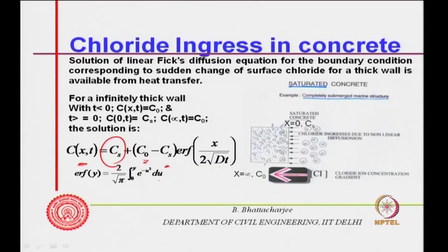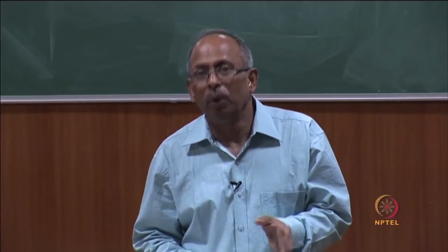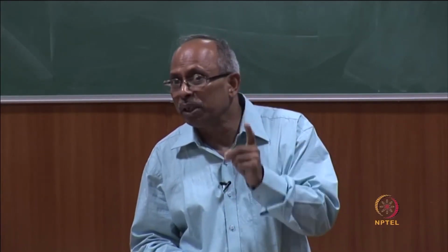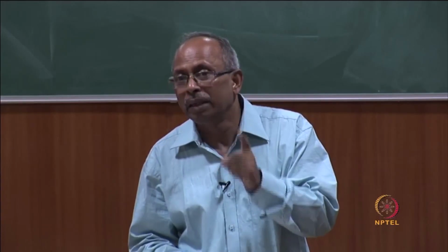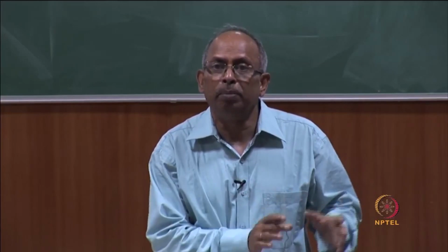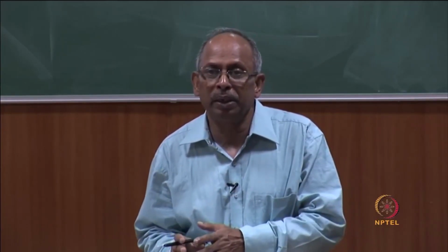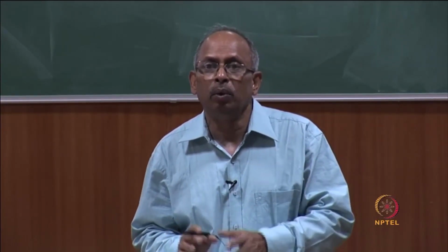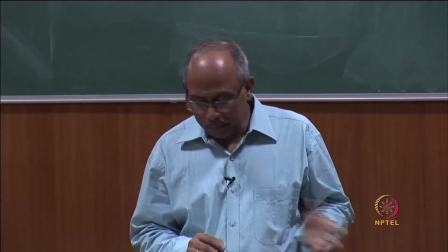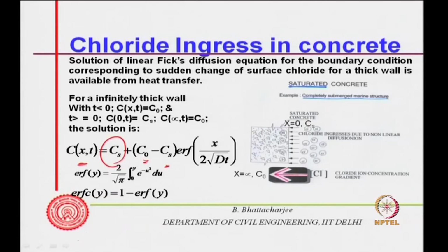So, this is a known solution, but this is not valid for all situations, although apparently a lot of people use this for all kinds of situations. It is only valid for saturated conditions, that means possibly where there is no splash zone, submerged concrete, where the concentration outside is constant, tranquil water, no change in concentration, and this boundary condition is followed. It cannot be used everywhere, but that is what has been done quite often.